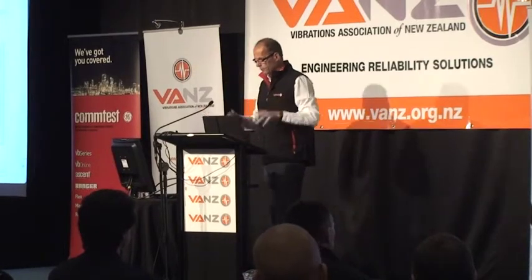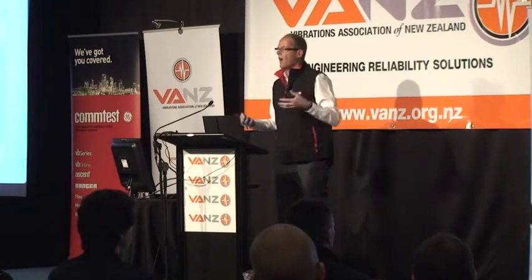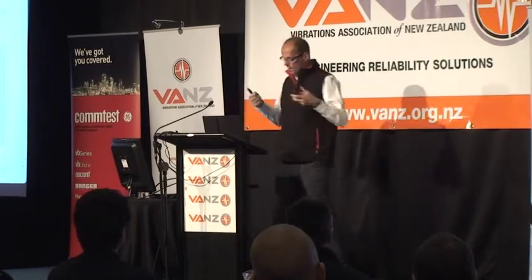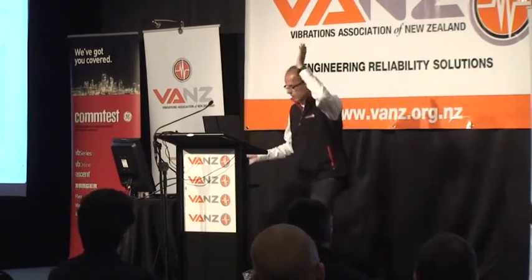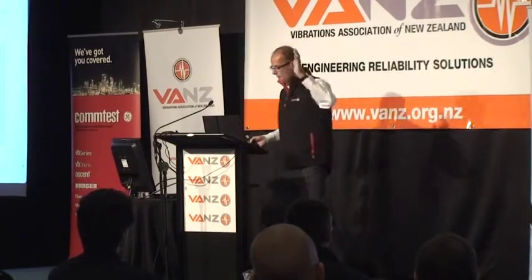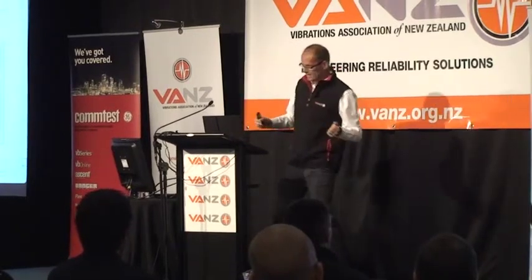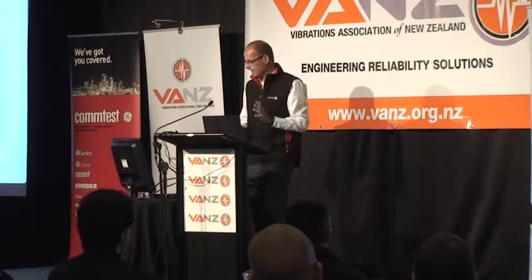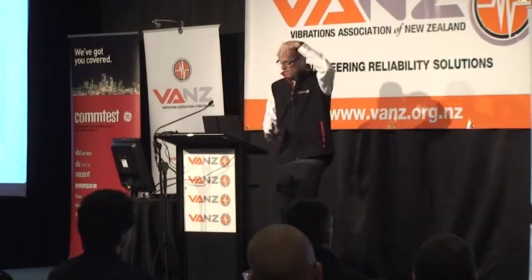Well, that's unfortunately not the case. It's also true that, if I had an unbalanced problem, I might move in this sort of circular motion, which creates vertical and horizontal vibration. I might have more horizontal vibration if the machine found it easier to sway from side to side rather than up and down. But, in that case, measuring in the axial direction wouldn't tell me very much.